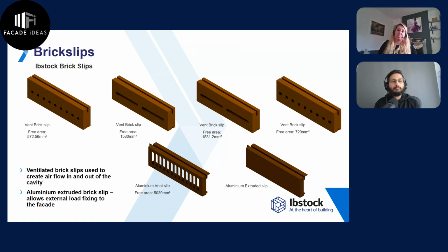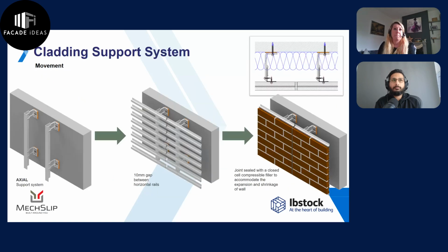that you may require. And also, if you are looking to support lights or signage outside of your buildings, we offer this aluminium extruded slip so that you'll be able to fix directly back to that. But again, I will say collaboration. It will take a lighting or small signage, but if you're looking at something heavier, we need to fix back to the main structure. It's all about talking to your supplier and collaborating to understand the principles of the cladding system that you're specifying.